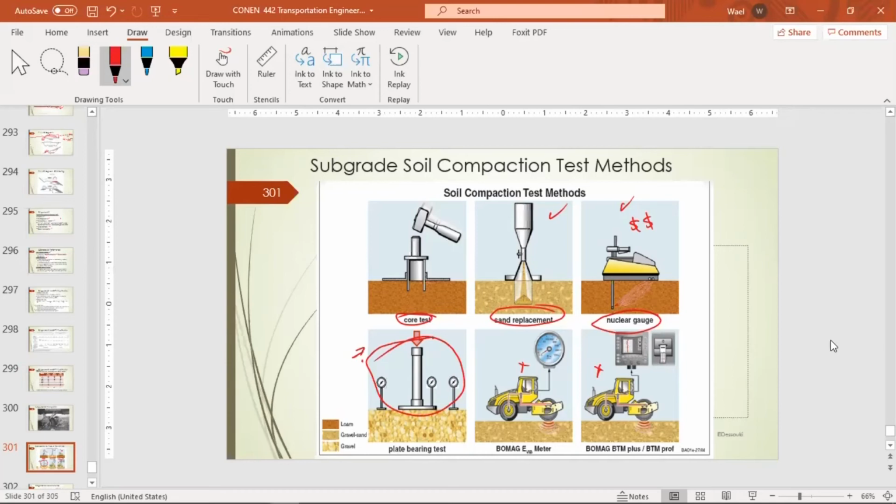But the sand cone test is very easy to apply and very common and cheap, doesn't cost that much. However, this test can be cheated, unfortunately. So for you as a construction manager or someone on the site, you have to keep a good eye on the sampling and make sure that there is no foul play in this test.